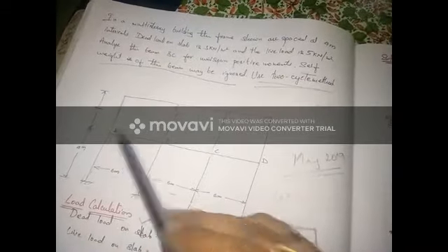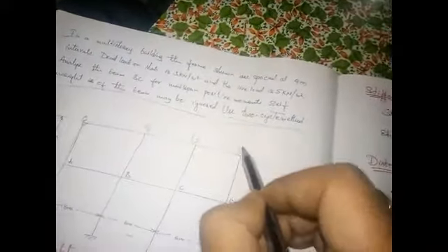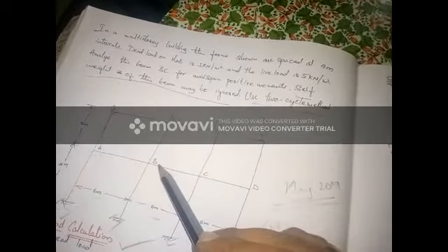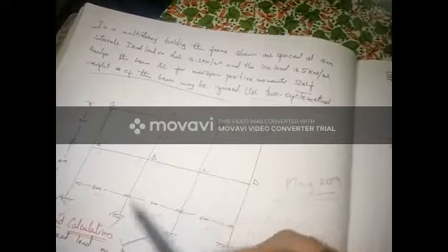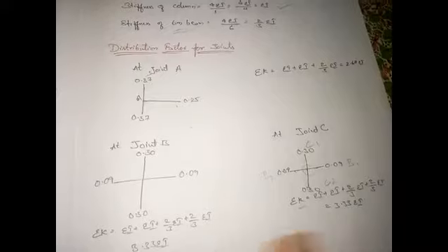That is, if we take this frame, we are supposed to take AB separately, then AC, or E, F, G, let's suppose, and I, J, K, L. So AE, AI. If we take BE, BF, BA, BC and BJ, all these members we are supposed to take in a tabular form, and the tabular form goes on increasing. So the best process for analyzing these multiple frame structures is through joints.